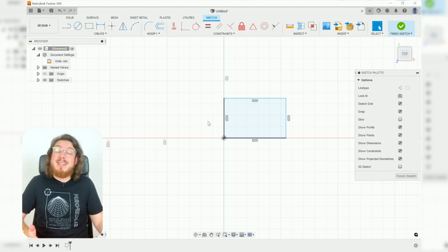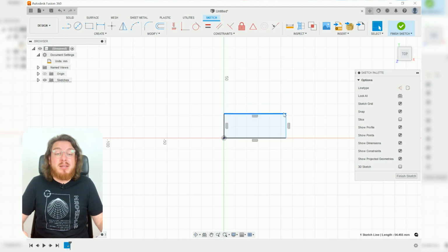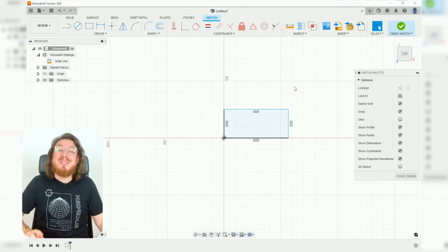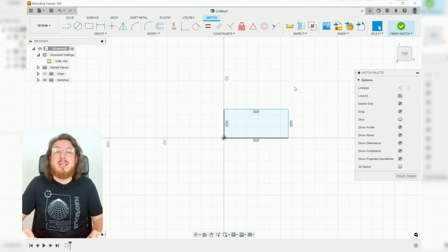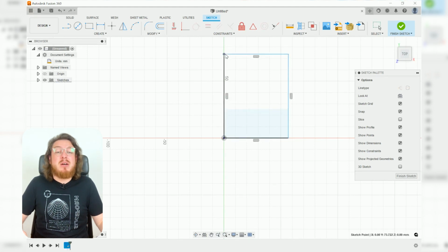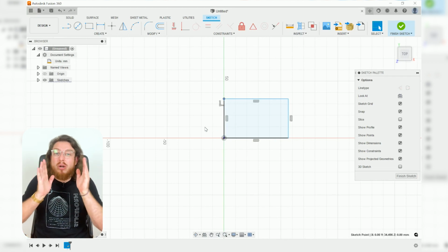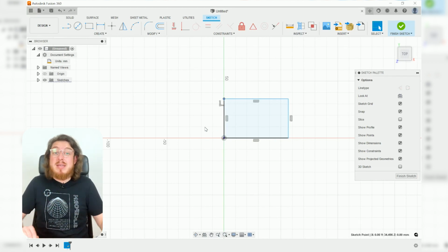In the world of CAD, saying that something is defined means that its location and dimension are completely known. For example, if my blue line is movable and I can change its size and location, then it means it is undefined. That's not a good thing. In Fusion 360, anytime I'm making a sketch, I am not done until all of my lines are black. That's what we're always going for. Now these lines are black, their end pieces aren't, which means that we can change their length, but the actual line itself is locked in the right location. So that's why they are black.